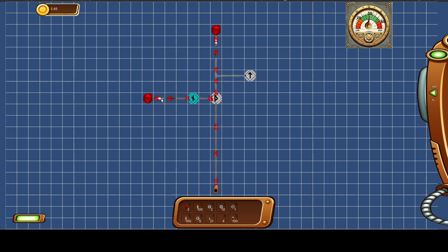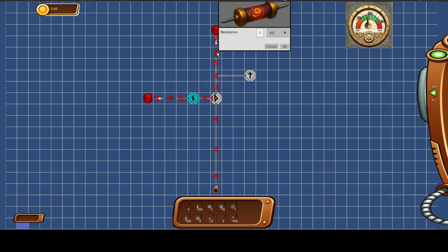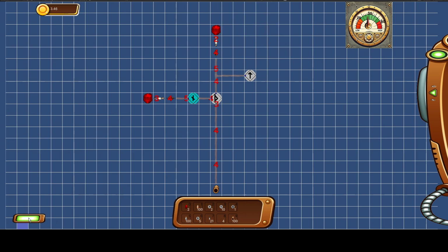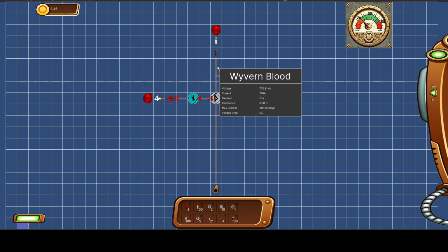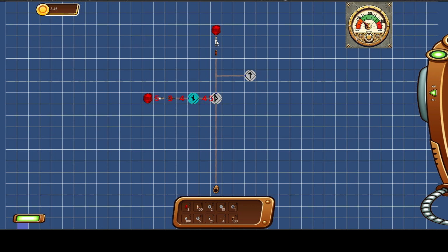So the fuse is there because, I can probably just show you what will happen here. Let's take this resistor. It's a 1 kilo ohm resistor. Let's drop it down to 1 ohm and let power go. It's weird those guys kept going after this thing shut off, but anyhow, you can see this fuse has blown, and so now there is no longer any current running through here. There shouldn't be any voltage, so that's another bug that will need to be resolved. They wouldn't have kept going if that thing had properly responded as if it were an open circuit, which is what it is right now.